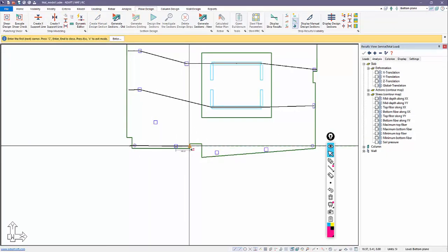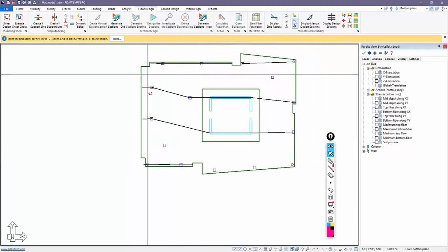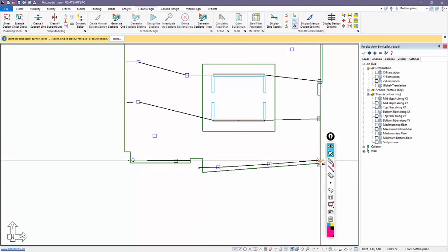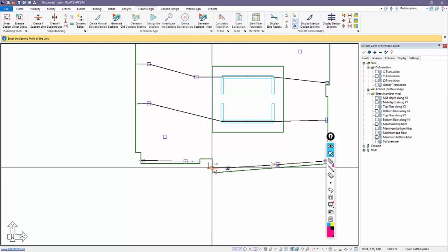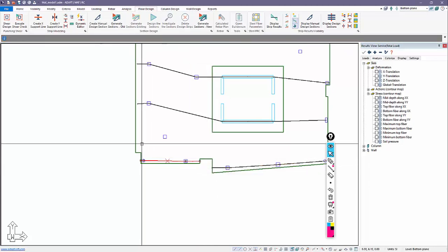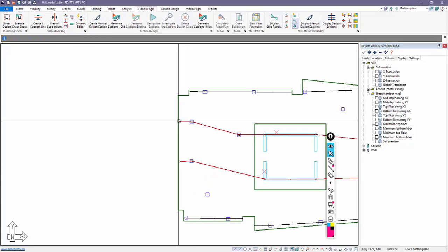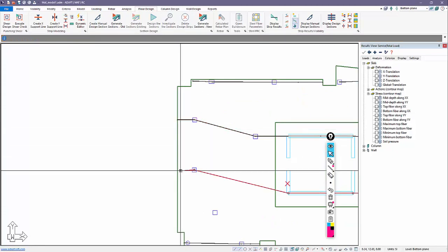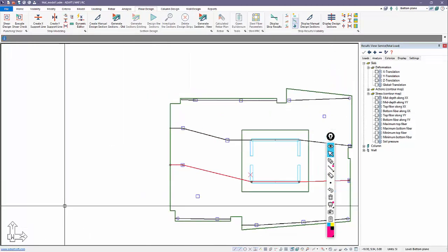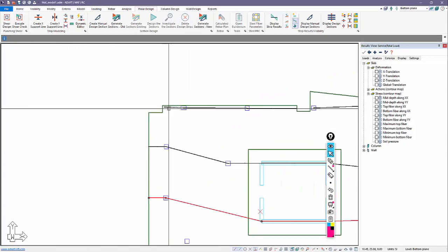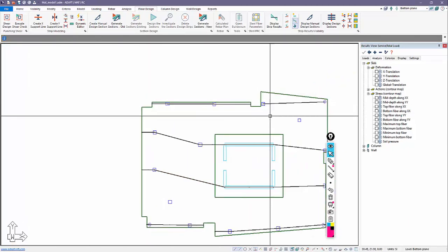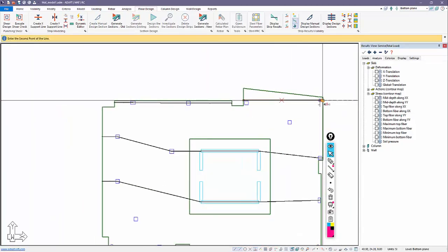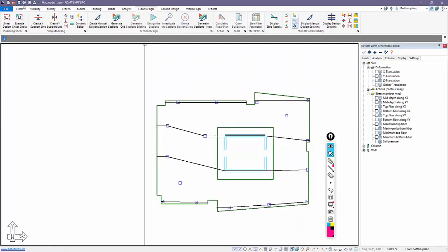And you can see I'm a little bit loose in how I model these endpoints. I'll come back and clean them up and snap them to the slab edges. So if we use snap to perpendicular, we can come back and just move these to slab edges. They really don't need to be moved technically, but if you want to see them, I guess, more cleanly identified and have everything perpendicular, let's say relative to these global axes, you could post modify the endpoints like so. Okay, these ones I'll just stretch out, maybe there and there. Okay, that's the X direction.